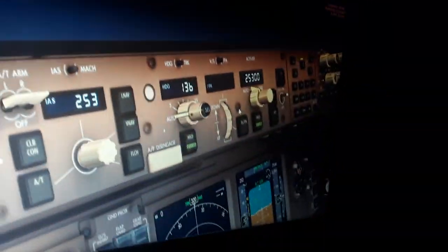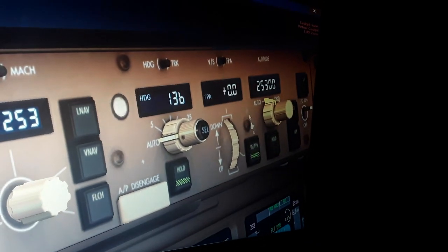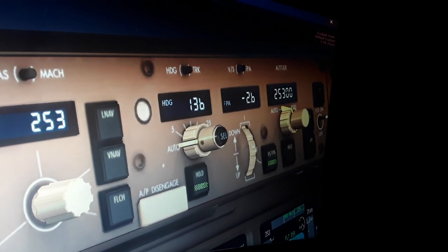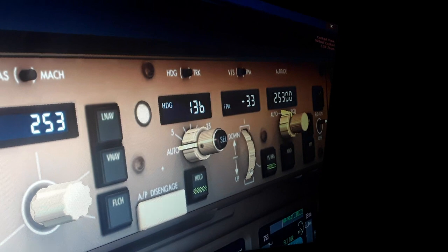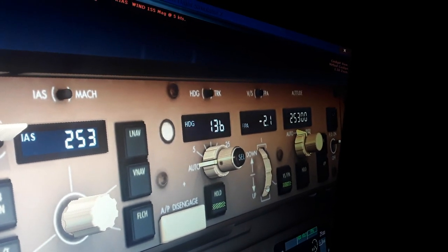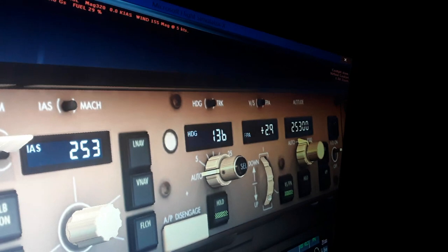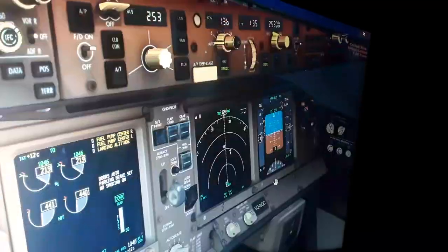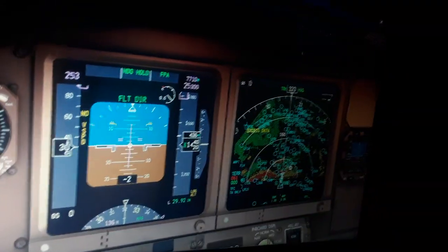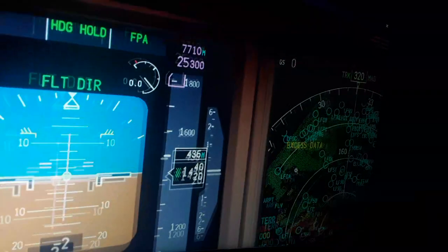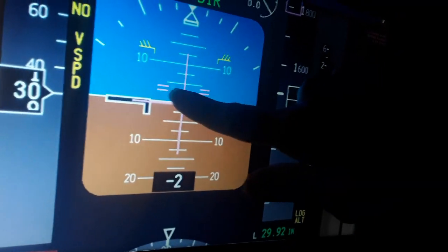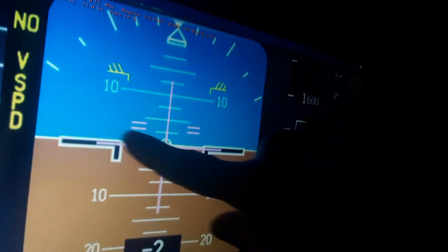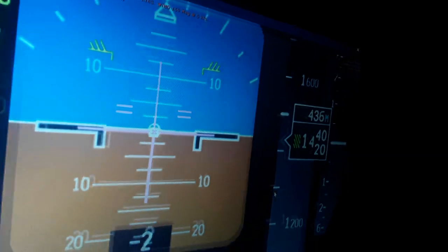So a couple more modes we can tweak, like flight path angle, vertical speed. So you can see the minus here is negative, so it's descent. Now I'm going to come to the plus, it's going to be a climb. So you will see plus 3.5 degrees for this mode, which interconnects with the other, the flight path angle. So you will see the flight path angle after takeoff to 3.5 degrees, which generally speaking is the same as the other modes for after takeoff pitch.